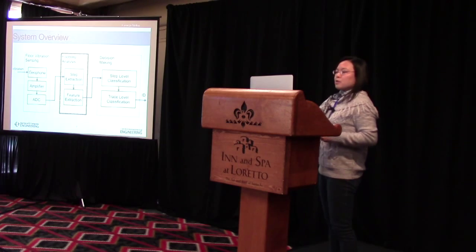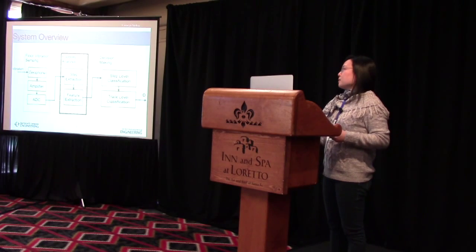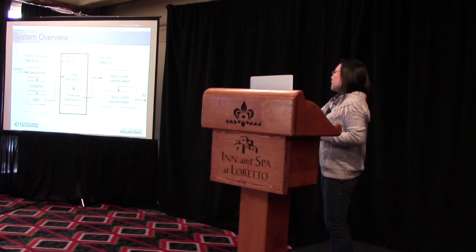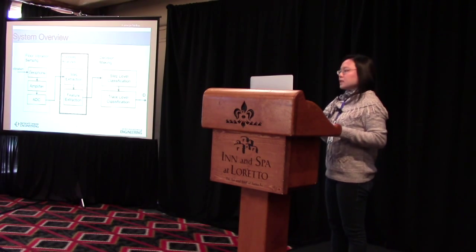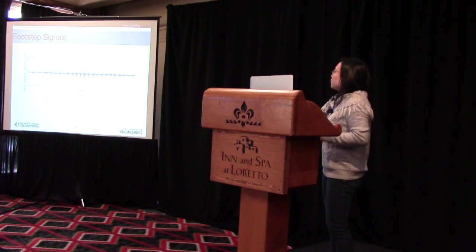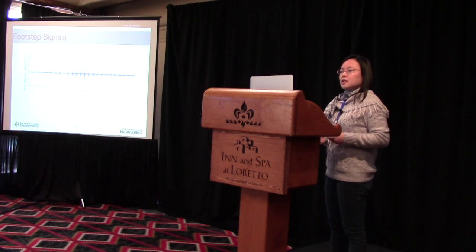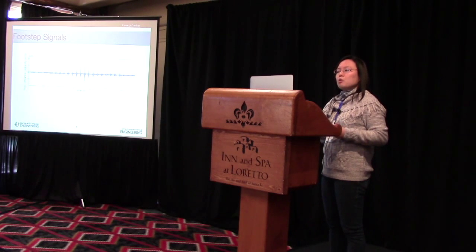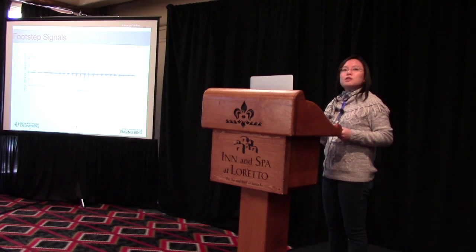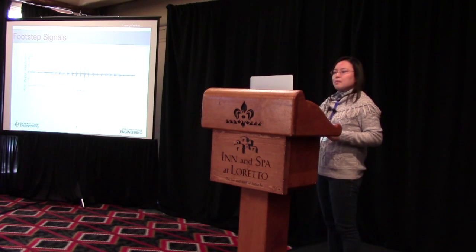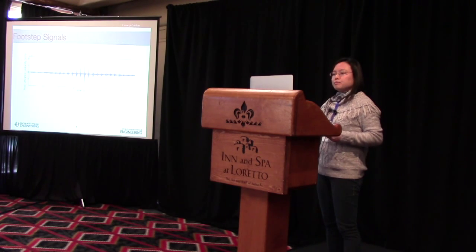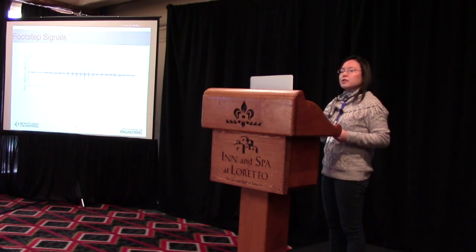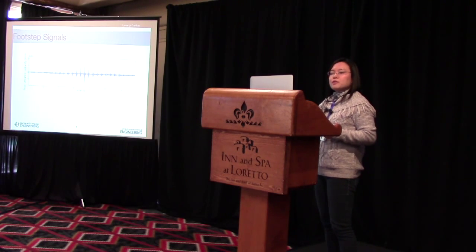The second module in our system is the footstep analysis module. Signals induced by footsteps are obtained first, then the features are extracted from these signals. Now we are going to talk about the step extraction first. This figure demonstrates a segment of signal collected from a person passing by one of our sensing nodes. The x-axis is the time in seconds, while the y-axis is the velocity we measure of the vibration. From this signal, we are going to extract those signals induced by footsteps.